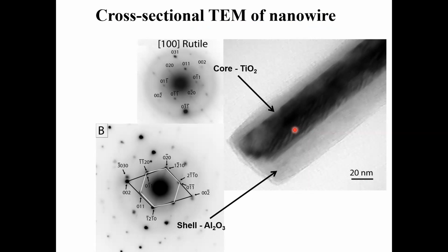But if you deprive the oxygen content to tens of ppm, then you grow this one-dimensional oxide. And we were able to confirm the reason for this in Ti6-4 alloy, for example.